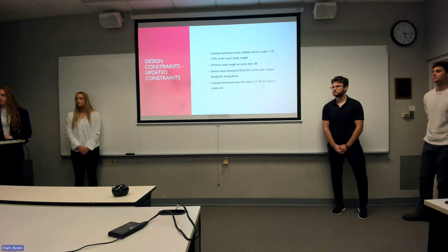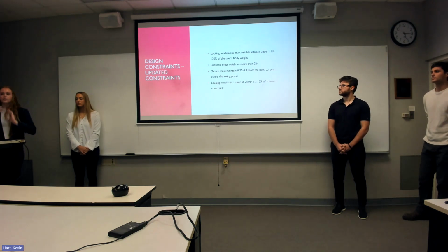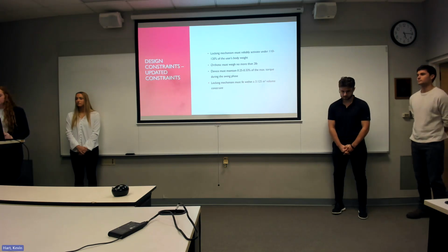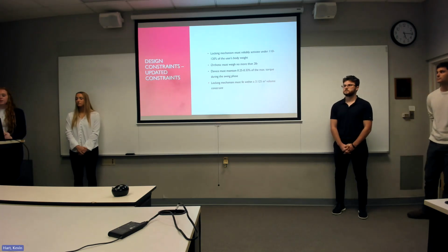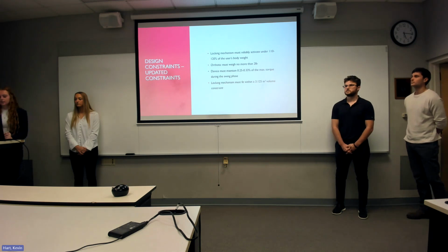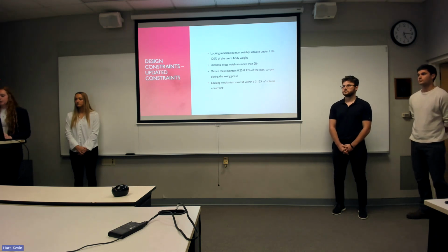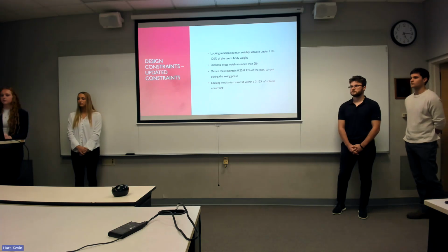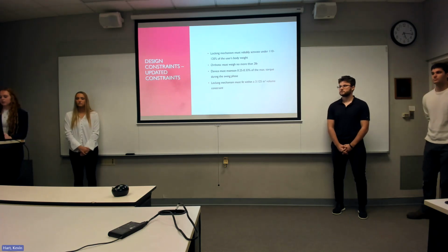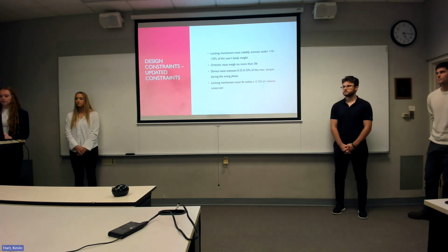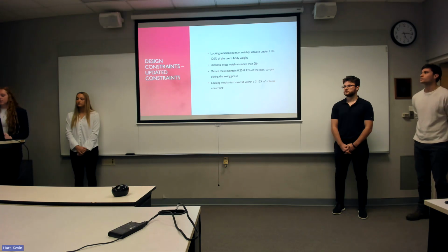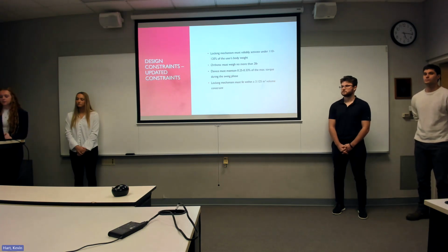Similar to our objectives, we refined the design constraints, getting help from Dr. Liu, Dr. Rizza, and Tom Current from Hanger Clinic. Our updated constraints are more specific and more realistic. Instead of generic force limits, we now require the locking mechanism to reliably activate under 110 to 120% of the user's body weight, which reflects the actual load seen during the gait cycle.